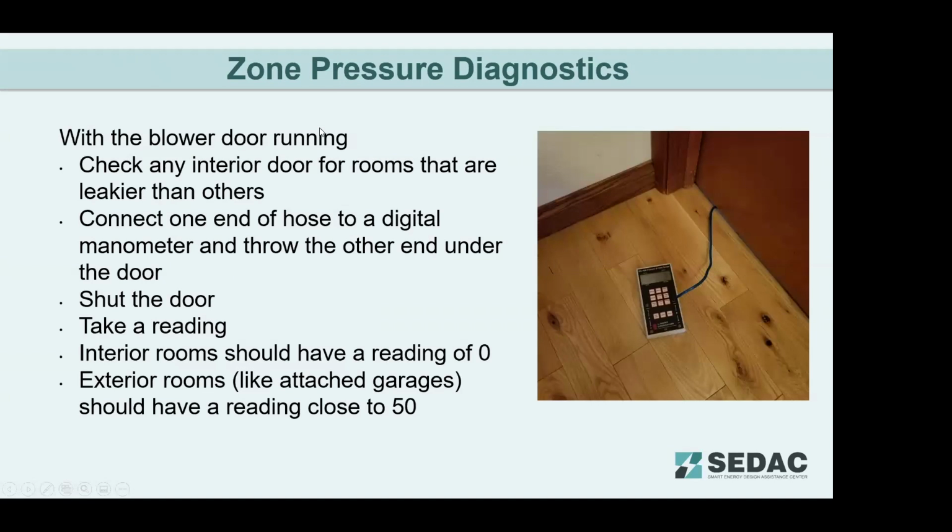Actually, I don't have a slide on look, listen, and feel. But basically, you're going to walk the house and quite literally feel the air leakage. The blower door creates an effective 20-mile-an-hour wind on all sides of the house. Again, I'm referencing CFM 50. So you can walk up to a window or a light fixture or a penetration, and you can feel the air coming through it.